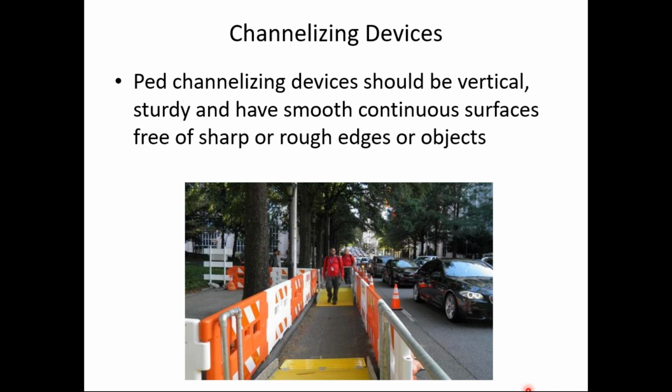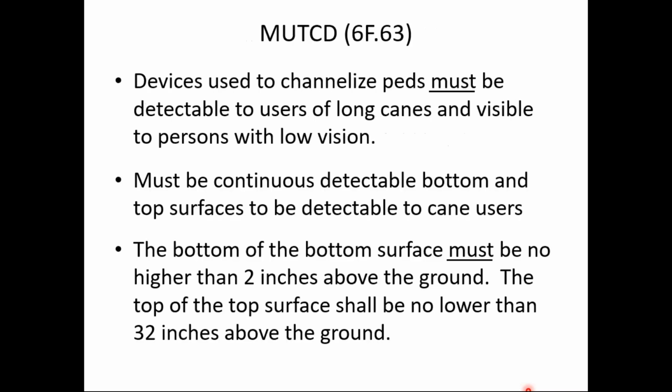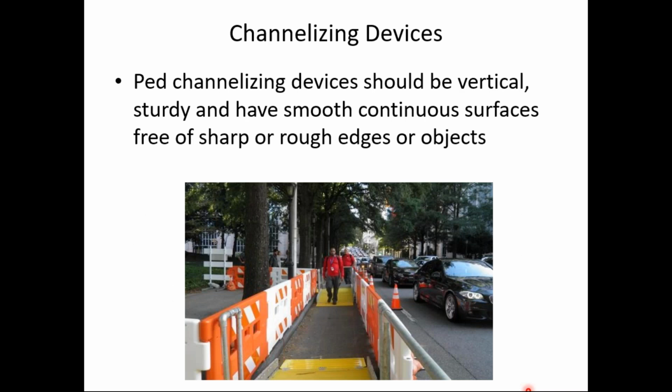Let me give maybe a couple of extreme examples. I know there's a big gray area in between, but for example, the driveway to a single family residential home. I would argue a driveway for a single family home doesn't look or act like a street, so I would not put detectable warnings there. At the other extreme, we might have a private driveway that serves the regional shopping mall, and it's probably multi-lanes wide, right?